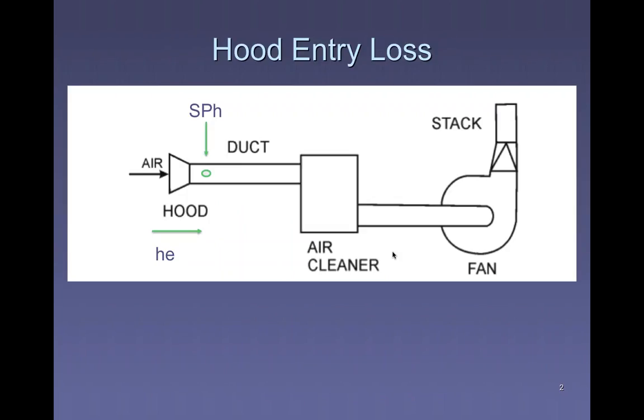Anyway, this is where we're going to measure our static pressure for the hood. We're going to use what we know about this hood, the equations, the manufacturer's information, and we want to determine what the static pressure is, how much suction you need right at that point. What static pressure do you need at that point to deliver the amount of airflow from that hood, the capture velocity that you want to protect the worker? Okay, and the static pressure, what is that determined by?